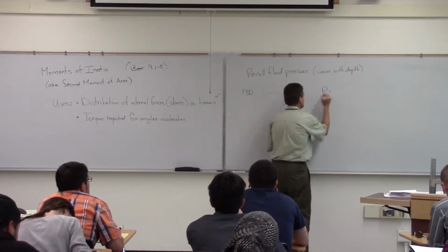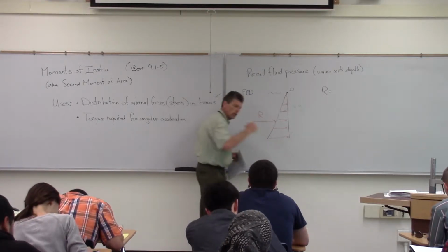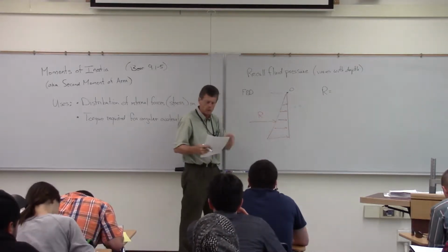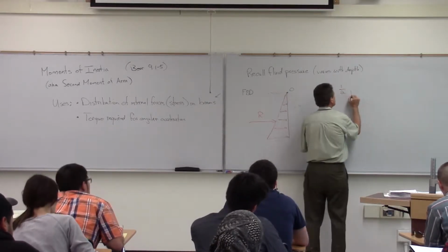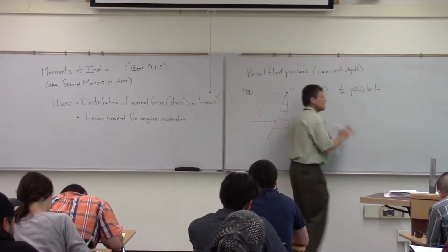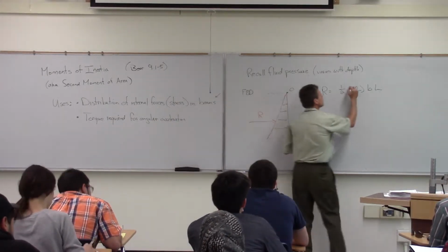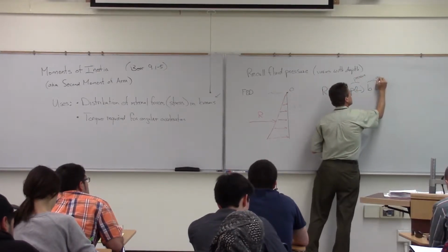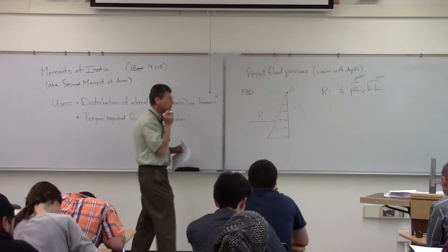But again, to calculate that equivalent force, remember, it was just simply that triangle, but also remember we had that width to worry about, b. So it's that triangle, so we start off with 1/2 times the pressure at L times the width, b, and then times the L. So this is our pressure. And this is our area. Remember, pressure is going to be force divided by area. We multiply times an area, we'll come up with an equivalent force.